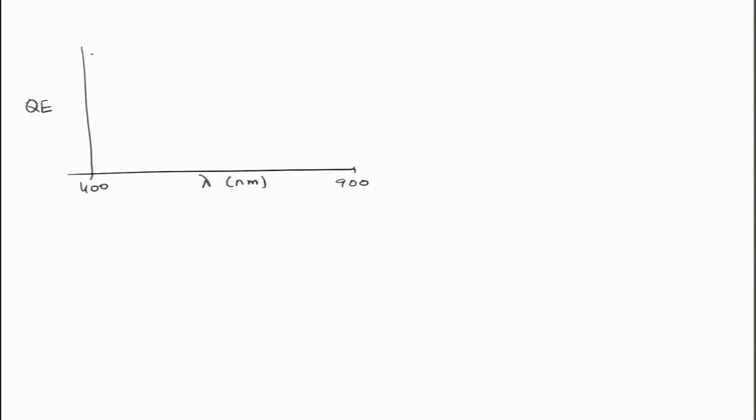So if your XP is thin for a certain case, let us say in the case where recombination is large, as you increase the thickness. If your Xn or Xp, whichever you may have, if your quantum efficiency is like this, and suppose you start making the layer thicker,